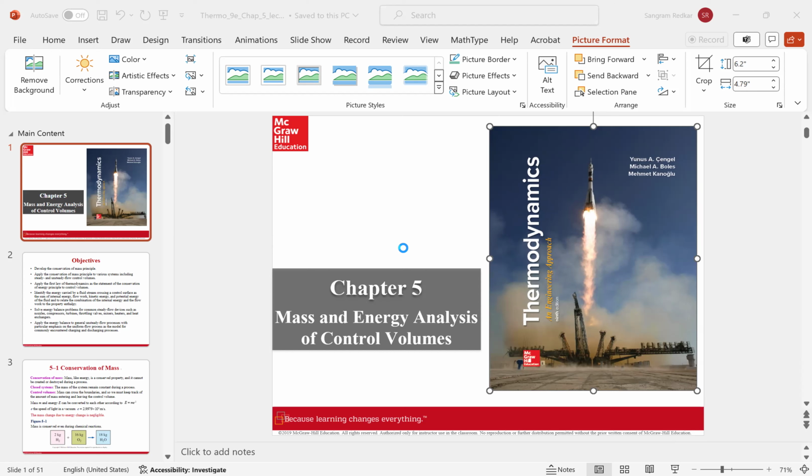So as long as we are looking at below 1 Mach, the nozzle is used to increase the velocity at exit. Diffuser is used to reduce the velocity at exit, and the energy equation, or energy balance, is given on the right hand side.